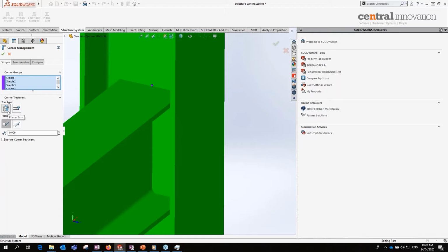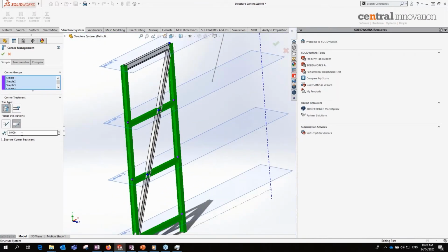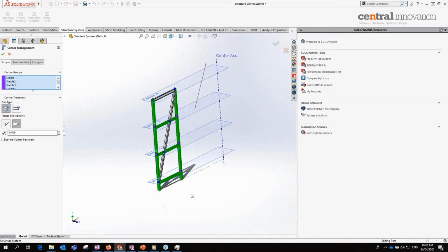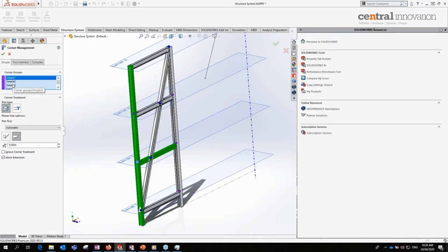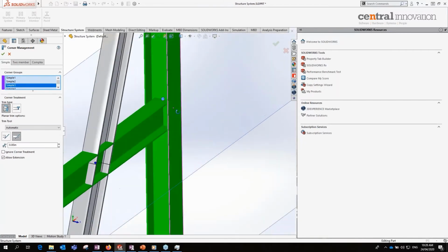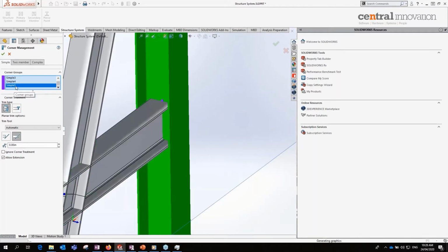But planar trim could be applied with 2 options. It could be either first contact plane trim or full contact plane trim. Yeah, this one will not be clear enough here. You can define a gap between them. I will switch now. So you can click on each and every connection to specify a particular trim condition.